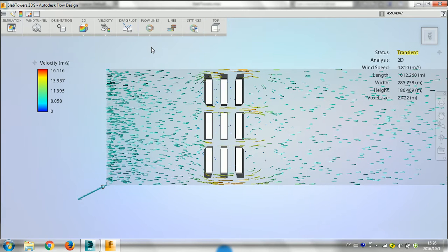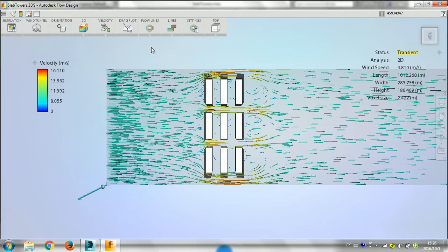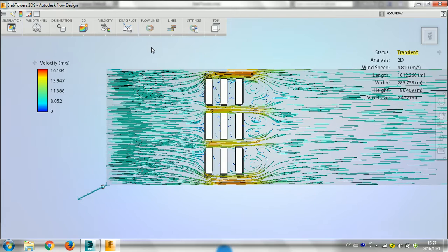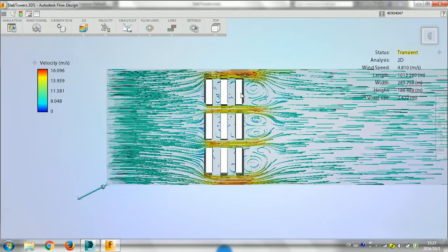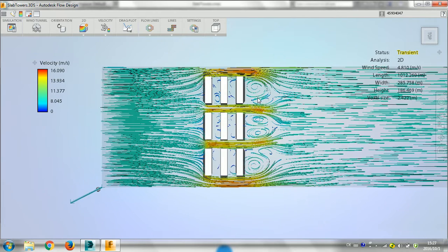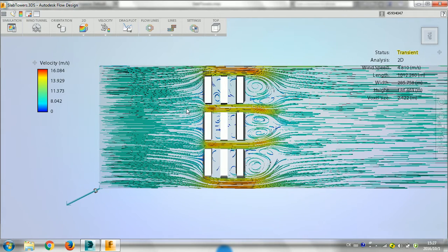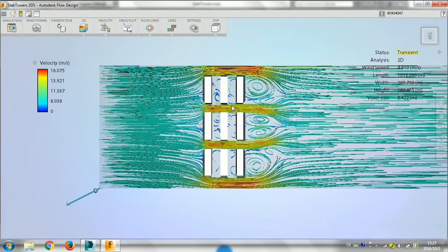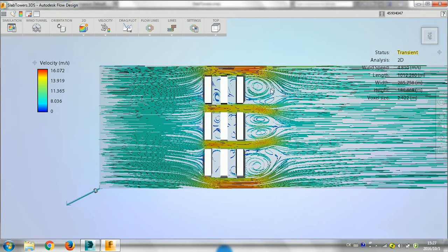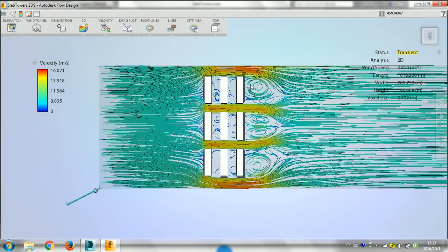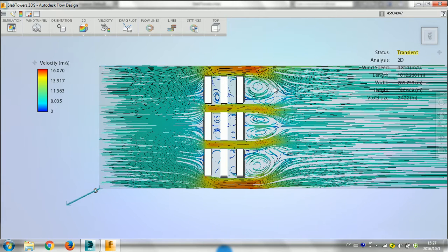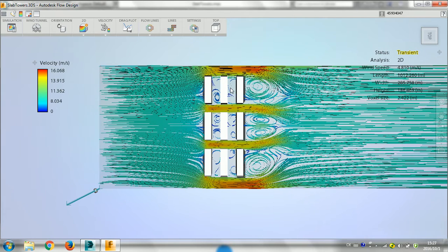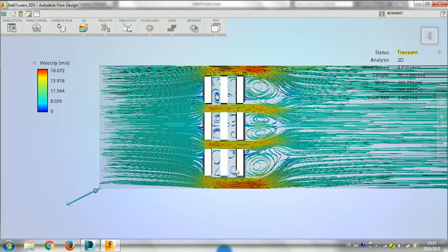Once that has been changed, you can see the movement more clearly than the previous setting, and we can now see that the wind, because of the Venturi effect, flows much faster in between those buildings. However, it also has a whirlwind effect behind the slab buildings, but in the middle of the buildings there's actually not much wind going on.